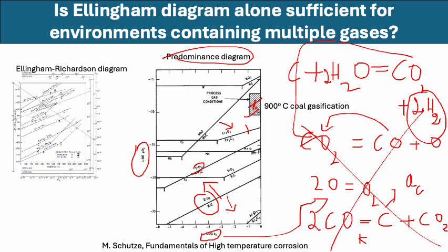If the structural integrity of a structural material is compromised, then there is no use in designing alloys that can withstand creep. So this is where the reactive environment plays a very important role in the high temperature properties of alloys. This needs to be borne in mind every time we work in these high temperature chemical processing or power generation technologies in the industry.